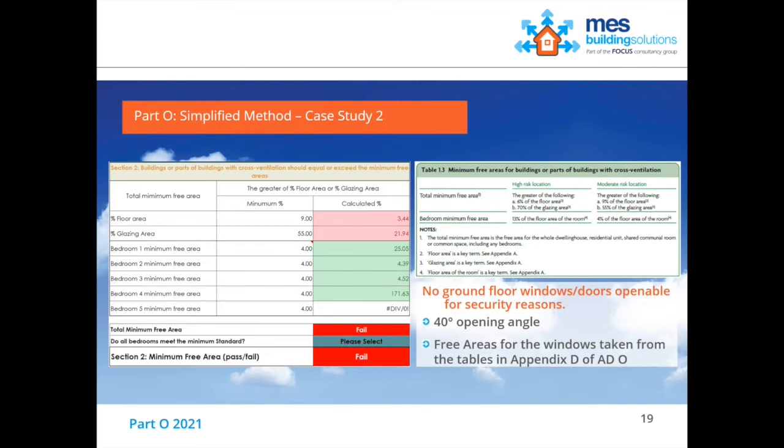What would the impact of that be? We can model that using DSM, because that models the airflow through the building and through all the different openings. So if you want to keep that fenestration design and we can't get it to comply with the simplified approach, that's one of the routes we're looking at. We'd then be looking at the full DSM approach to say, can we now come up with some options? What can we do to this space to make sure that it doesn't overheat?